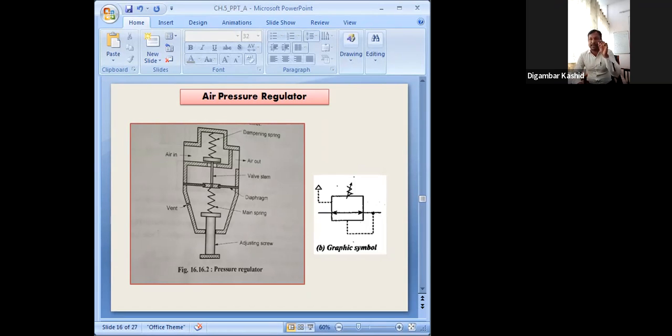For that purpose, the air should have the proper operating pressure for your circuit, and if improper pressure fluctuation is present in the piping system, then it can adversely affect the operating characteristics of system components such as valves, cylinders, etc. So you need to regulate the pressure of the incoming compressed air for our purpose, to achieve the desired air pressure at a steady condition. Getting it?